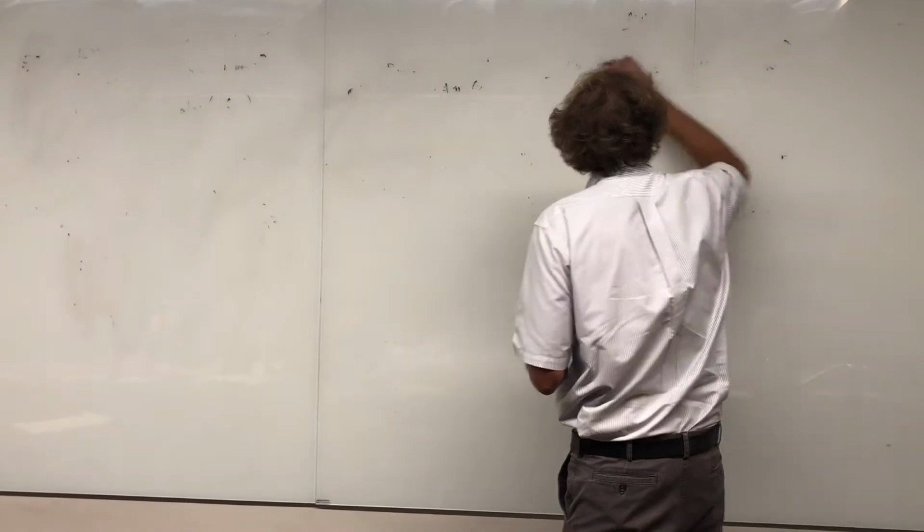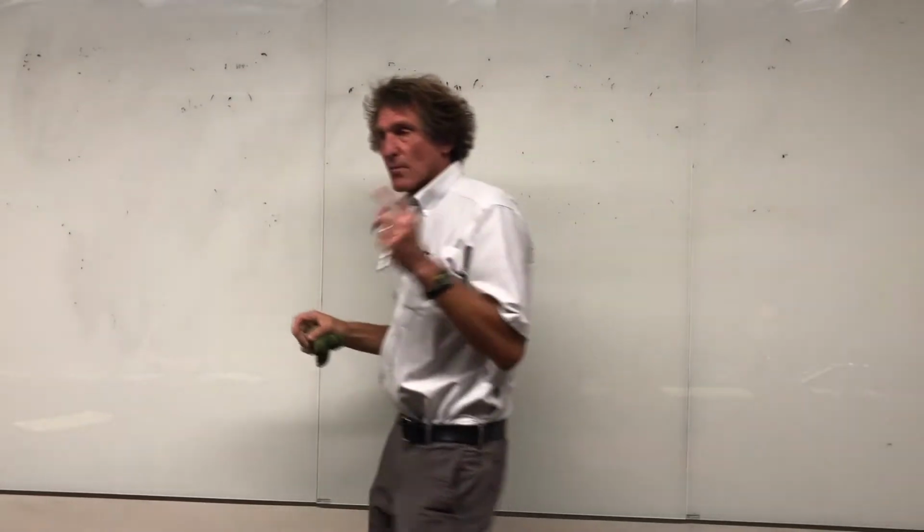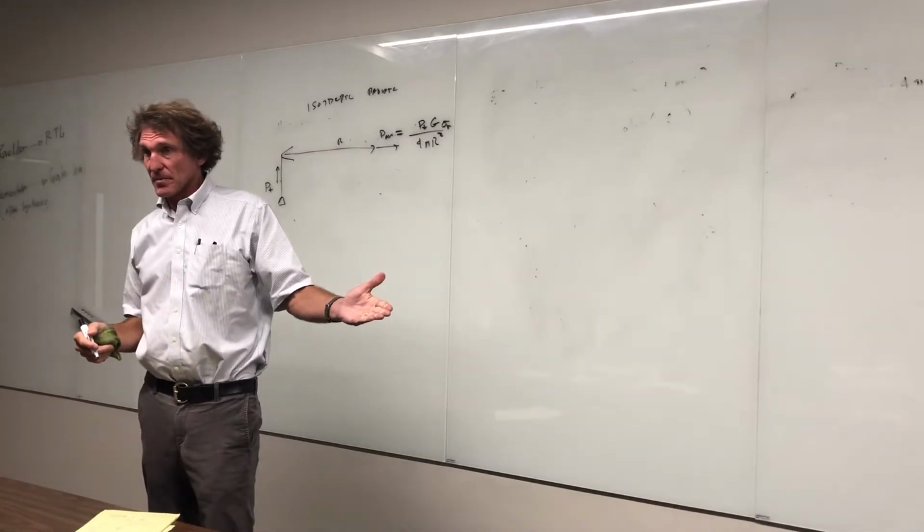And one other thing I'll tell you with antennas, there are 2 things you always look for. This is just the technical bit. You always want to take a look at the max gain. You always want to take a look at how far down the side lobes are. If they say 20, 30 dB in side lobe, that means it's 20 or 30 dB less power in the side lobe than it is from the main beam.